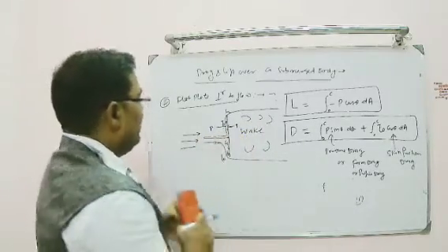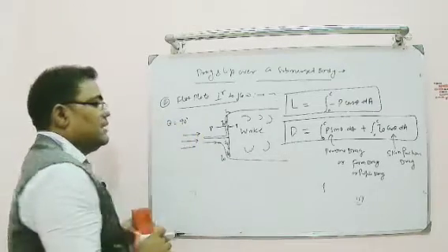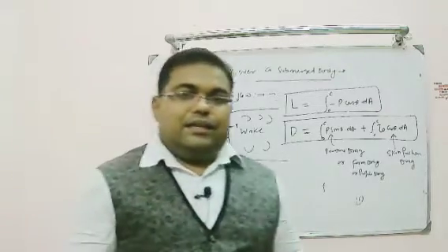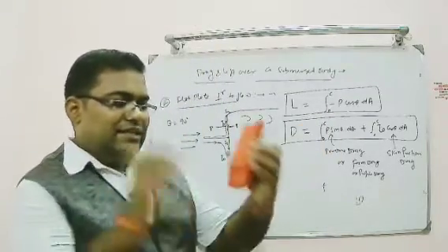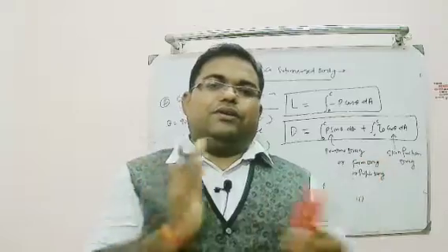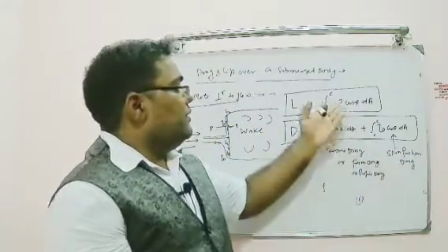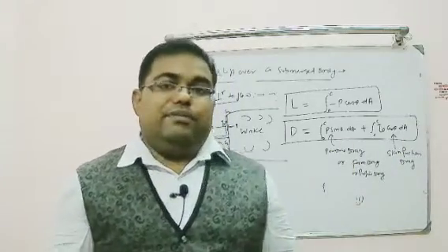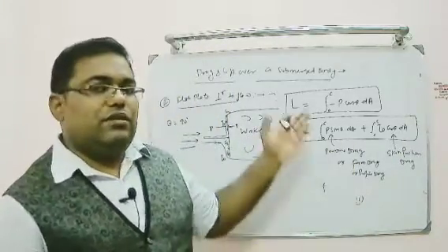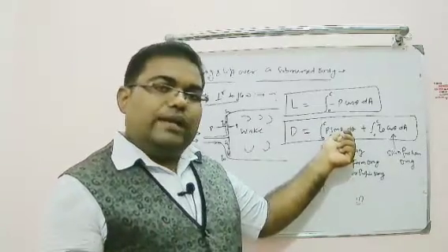If we look here, the flow deflection angle theta is equal to 90 degrees. If theta is equal to 90 degrees, we will not get any kind of lift. Basically, the flow is directly hitting the surface and getting separated from top and bottom, so lift is going to be zero. Only there will be drag, and that will be a very big contribution of drag, called pressure drag. Sin 90 is equal to 1, we know.